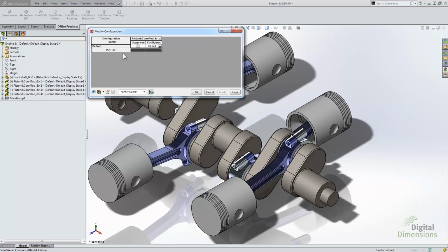I'm going to do a configuration handoff here. I say handoff because you can't just drill down straight into the part level. We have to grab a configuration of the subassembly, and then that subassembly has to grab the configuration of the part itself. And again, the ability of saving tables at the assembly level here.